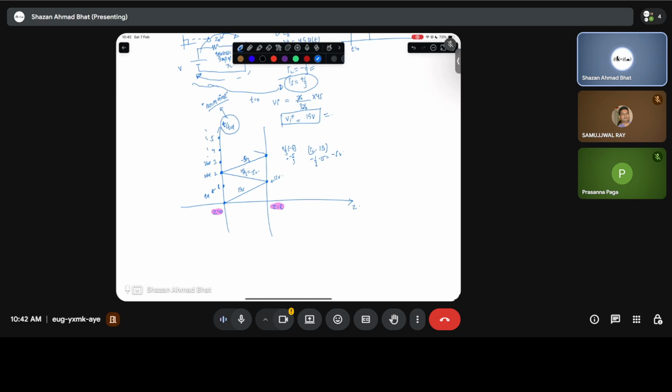And again, it will get reflected towards the source end, and the voltage will be divided again by 3. So this number, minus 5 by 3, which is around minus 1.67, will be divided again. The sign flips again, so it will be minus 1.67 times minus 1 by 3, which is 1.67 divided by 3, around 0.55. So it'll be 0.55 volts. There'll be no negative sign here. Now it'll again get reflected, and after time 5 TD, again it will be divided by 3, so it'll be 0.21.